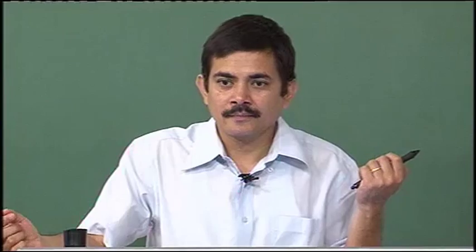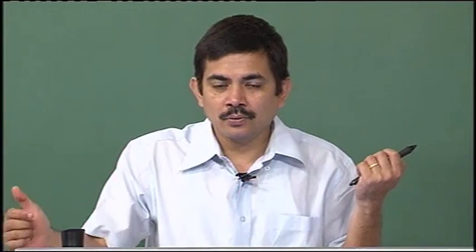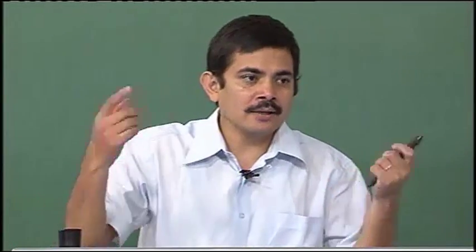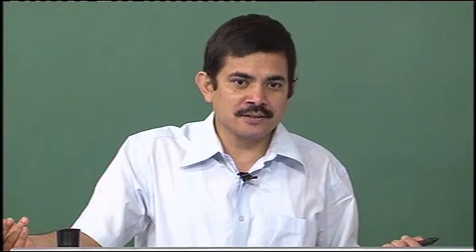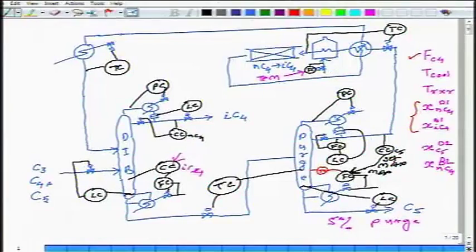Whatever is leaking down is leaking down. It's not in your hands. I don't want that, because I know from my analysis that boil up does become active. Boil up does hit the max constraint. Yes or no? So what do I do? Okay, I don't do it this way, I do it that way, by adjusting the feed.